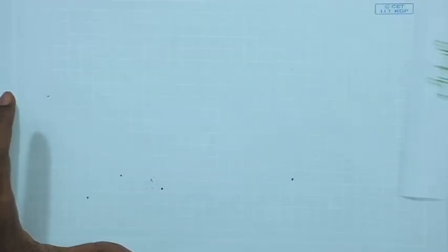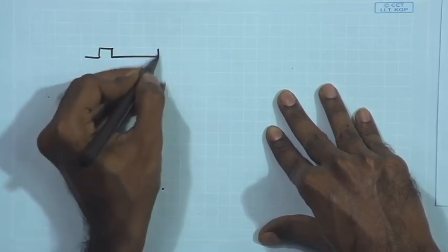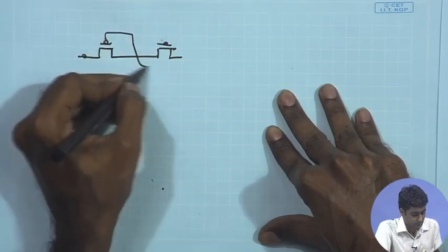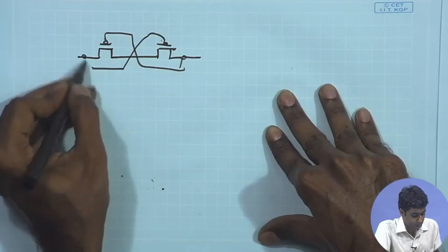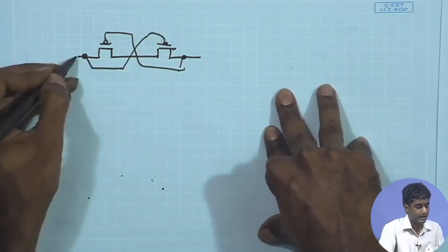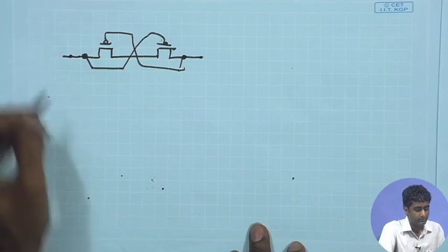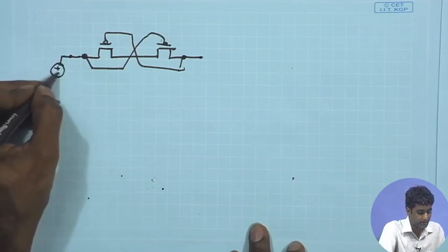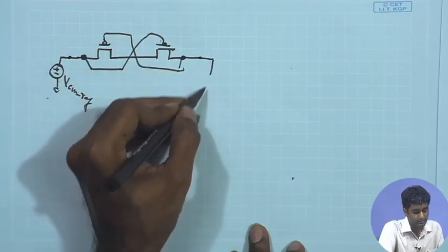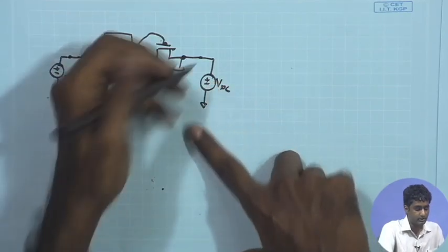If you look at the RF, the way we created it using the transistors, remember the connections are only at the dot. Wherever you have the dot, there is a connection; otherwise, no connection. And here also, in order to characterize this and try to find out the impedance of this, one easy way to do it is apply a DC potential over here, which is VCM ref, and then apply some VDC over here, and in the DC sweep analysis, basically you can try to